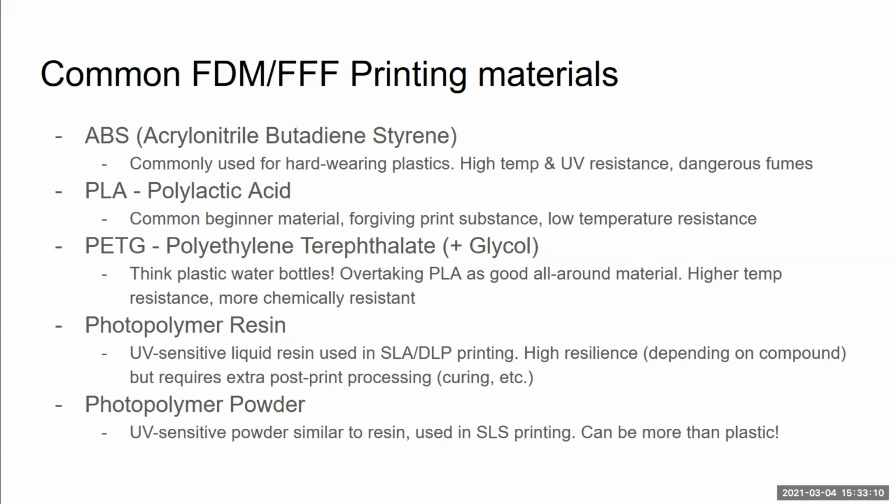But it's difficult to 3D print because not only is there a high thermal load that has to be overcome in order to melt that plastic, so the glass transition temperature on that plastic is really high, it's also potentially really dangerous because the fumes of ABS are really dangerous. They're potentially carcinogenic, so if you hang around printers that print ABS, there is a high likelihood that you have been exposed to cancer-causing materials, which is not great. The fumes are also extremely pungent, so it smells really bad too.